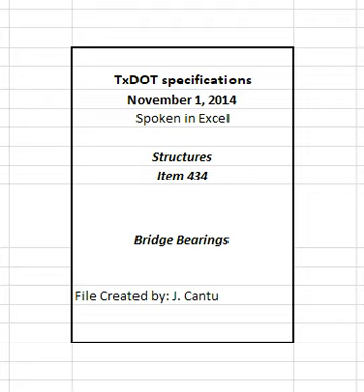The permissible variation from the dimensions and configuration shown on the plans for both plain and laminated bearings will be as listed in AASHTO M251, Table 2. Flash tolerance, finish, and appearance must meet the requirements of the latest edition of the Rubber Handbook published by the Rubber Manufacturers Association Incorporated, RMA F3 and T.063 for molded bearings and RMA F2 for extruded bearings.